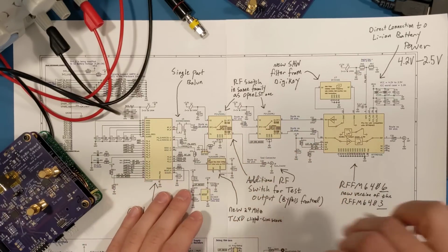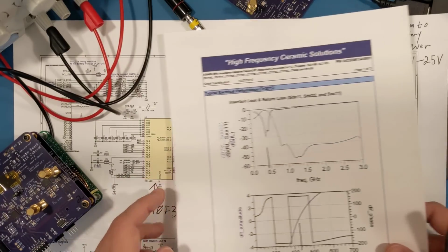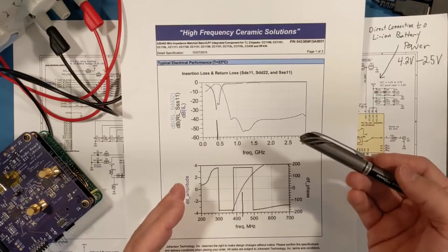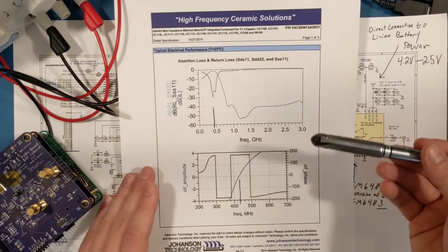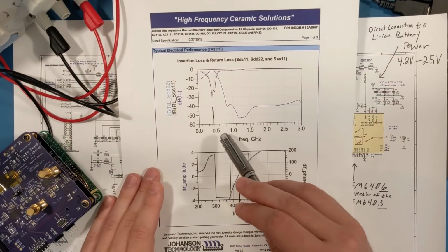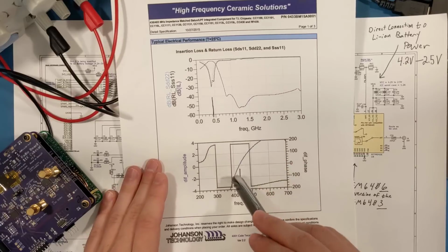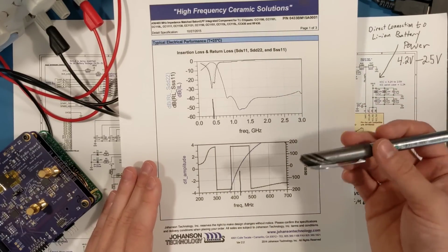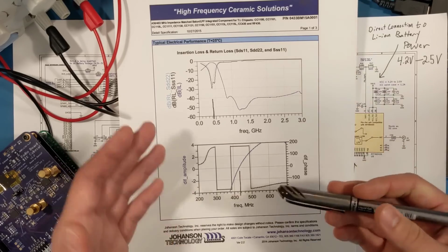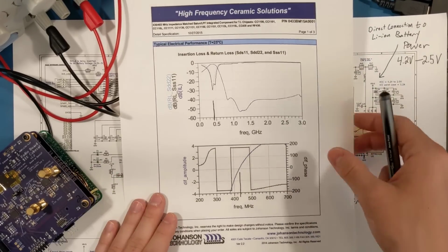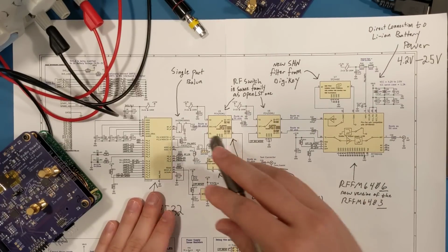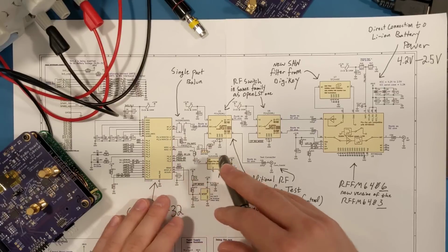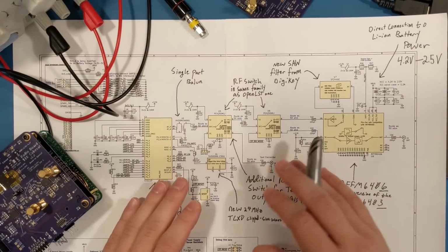And this isn't ideal, as the balun that I use is only specified for 430 to 435 megahertz. But looking at the provided charts with the balun's datasheet, it actually looks like 437 megahertz is pretty much going to behave exactly the same as 430 or 435 megahertz. Being off by a couple megahertz really isn't a big deal. That's true for the rest of the RF front end as well, where it'll work from between 430 to 440 megahertz without any issues.